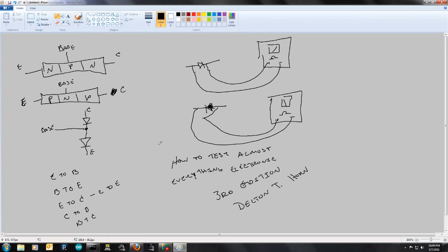Okay, guys, I don't know what the next video is going to be. It's one of two things. I think we're going to build a 5-volt voltage regulator, so we could stick 9 volts, 12 volts DC in, and have it come out a straight 5 volts. I think it's very simple. It's just 4 capacitors and a 5-volt regulator. I think that's going to be our next one, because I need to actually build one of those for a project